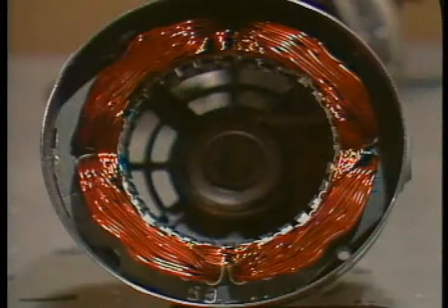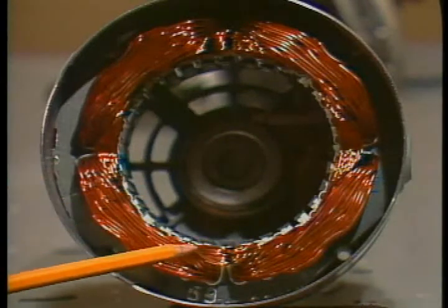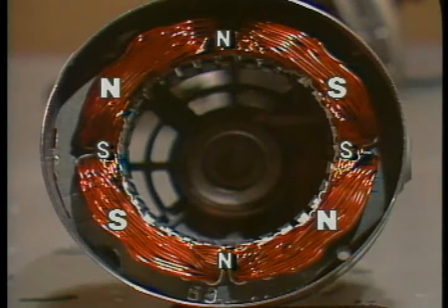To get them started in the right direction, most single-phase induction motors have two sets of windings, a set for running and another set to help during startup. The start windings are spaced around the motor, so their magnetic poles are between the poles produced by the run windings.